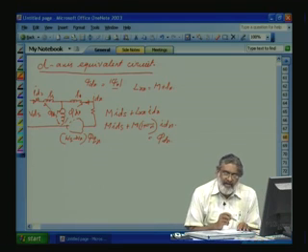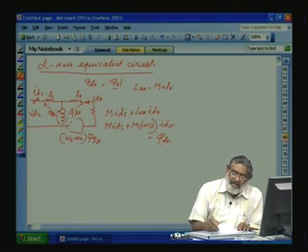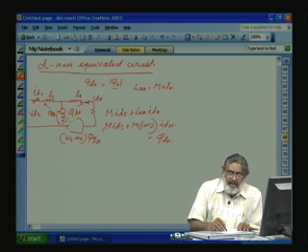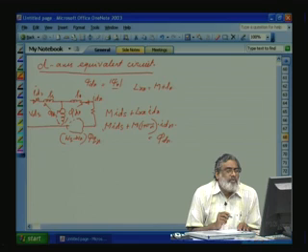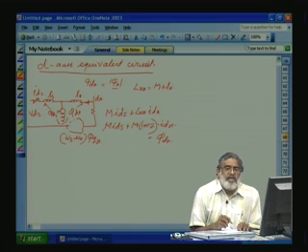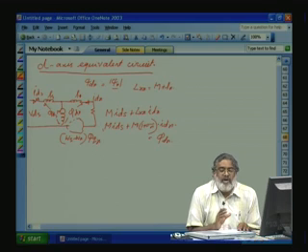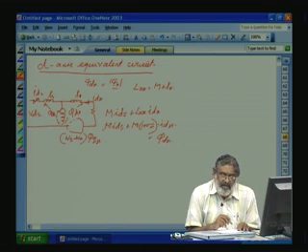So if you see here, this flux is the combination of inductance plus current, and we want to keep this flux constant under field oriented control. So IS we have to split along the dr and perpendicular to that one. When the component along IDR is kept constant, the flux psi dr or psi r is constant, because now psi r is along the dr axis.